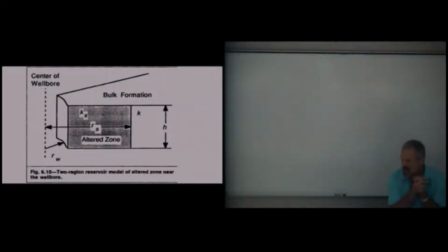When we drilled wells that were radial wells and produced them, we have a fluid in our wellbore. And who can tell me what that fluid is? Drilling mud? Drilling mud, yes. And what is one of the purposes of drilling mud? Preventing a kick. And how do you do that? Keeping mud weight density, have your hydrostatic head greater than the formation pressure.